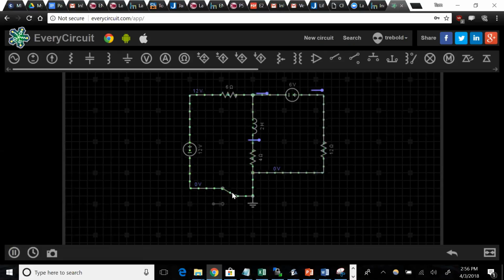But then what happens is you click on the switch, and this is sort of what's happening. You can see when the switch opens, what's not going to change? The inductor current. Everything else can change instantly, right? So here I'm going to click the switch, boom. All of a sudden, the current flipped in the 12 ohm resistor to go 100% in the opposite direction because the inductor was still driving it, right? And no current anymore in this outer branch. It's been disconnected.